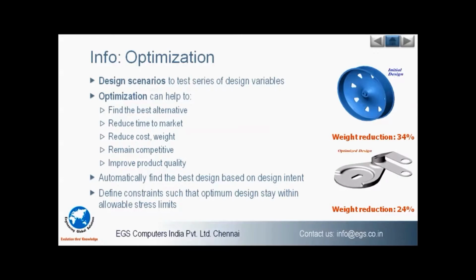And you can even directly link all the study results to the optimization. Say we were discussing the frequency analysis, even the mode shapes can directly be linked to the optimization study. Or if you are going to calculate the life from the fatigue analysis, the minimum life cycle of the product can also be taken as a goal to directly evaluate the product performance.